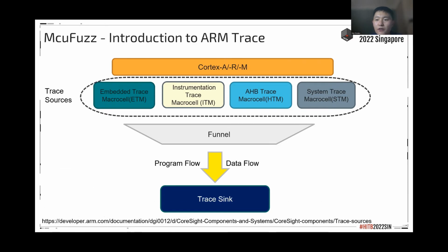They are called the trace sources, such as the ETM, HTM, ITM, STM. For example, the ETM provides processor-driven trace through an AMBA-compliant trace port. You can configure the ETM through the CoreSight APB programming interface. The HTM makes sparse information visible that you can't infer from the ETM. And the ITM and STM are application-driven trace sources that generate trace based on software written to the programming interface.